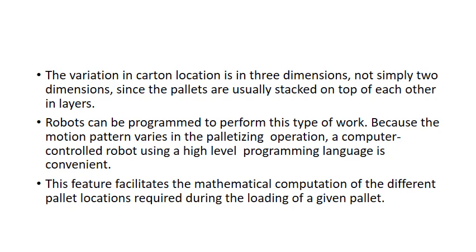Robots can be programmed to perform this type of work. Because the motion pattern varies in the palletizing operation, a computer-controlled robot using a high-level programming language is convenient. This feature facilitates the mathematical computation of the different pallet locations required during the loading of a given pallet.